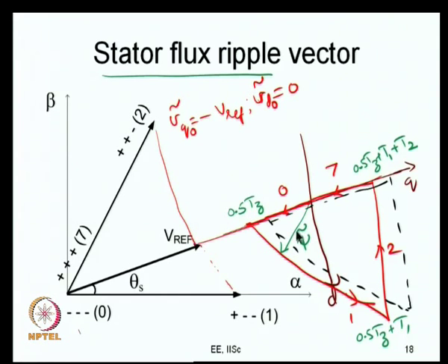The reason is this, that you have these unequal divisions, and I will stress this point more in the next lecture, when I would like to discuss certain alternatives to conventional space vector PWM, and say how they are different. But for now I am just making this simple point. You can see that there is an error in the q axis ripple, and the peak value of the q axis ripple is more, and therefore, the RMS value of the q axis ripple will also be more.